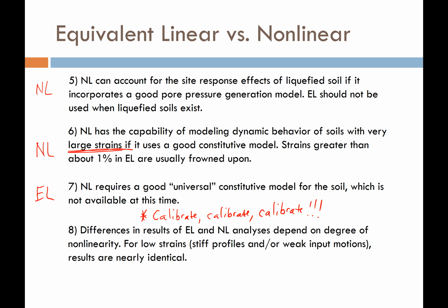Differences in results between equivalent linear and nonlinear analyses are going to depend on the degree of the nonlinearity. If I'm dealing with low strains in the soil, like less than 1%, if I have a really stiff soil and or weak ground motions going into the soil, there's going to be no difference between equivalent linear and nonlinear. And for those cases, I would almost always recommend the use of equivalent linear analysis.